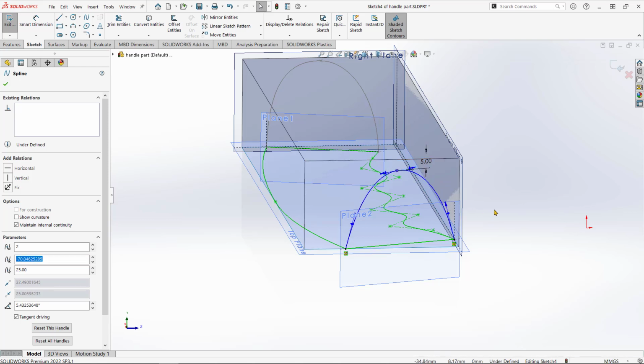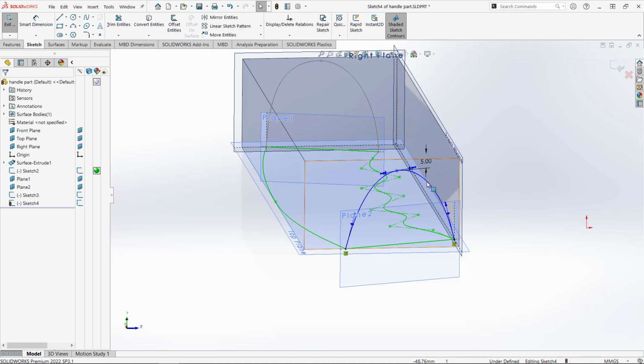What that does is it means that when I click off them, they will remain visible, whereas their initial state when you create the spline is that they are greyed out, and when you click off the spline they disappear altogether. So you just need to put some movement into them, any movement at all, and then from that point on they will always be visible.